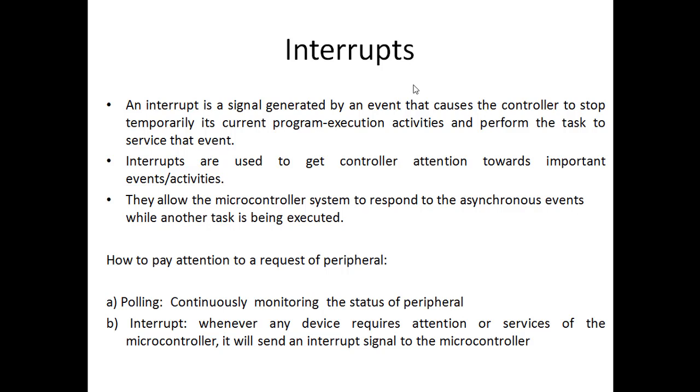Now the point comes why the interrupts are required. Suppose there are some important events which are happening which the microcontroller is unaware of. So let us inform it about that. To inform the microcontroller about the events which are happening, we can use our interrupts, right? Means to grab the attention of the microcontroller, we can use the concept of interrupt. Means interrupts are used to get the controller's attention towards important events or activities. Is it clear? And remember, normally your interrupts are asynchronous. Keep that in mind. They are asynchronous. So whenever an asynchronous activity is occurring and we want to inform our microcontroller about the same, we will use the concept of interrupts.